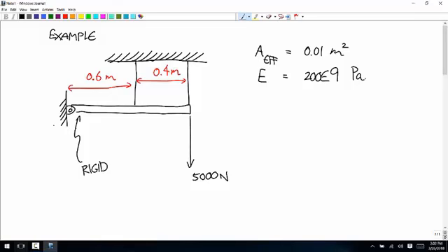First of all, what does that effective area thing mean? So cables are not the same as a solid metal bar of that same thickness because it's strands of metal that are wrapped around each other. So a lot of that area inside the shape, like if you just measured the area by taking the radius of the cable, you'd be measuring a lot of air in there. And so the effective area is the area that's made out of metal. Okay, so you wouldn't get that by measuring the outer diameter exactly.